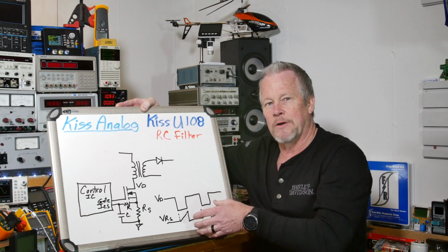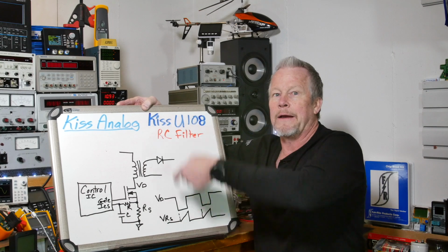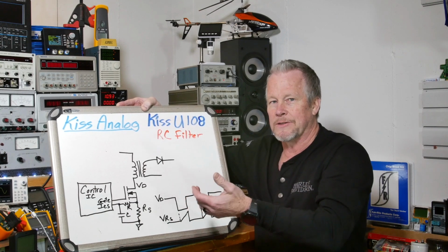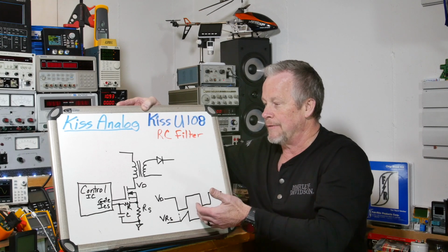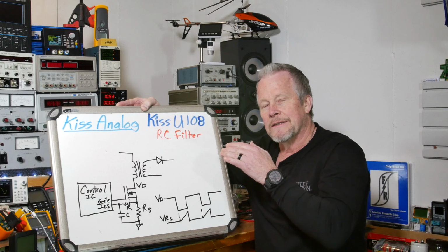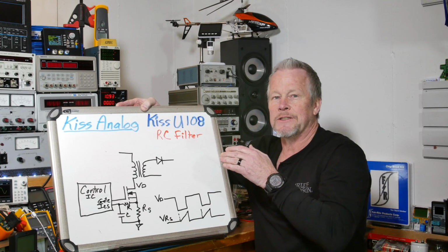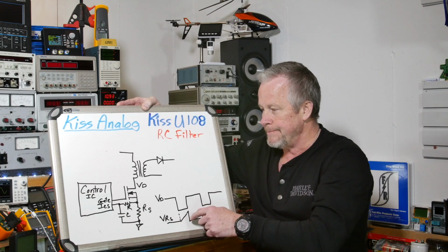It's just the inverse for an inductor. The voltage can flip. You get that kickback voltage, right? On solenoids and magnetics, you can get a kickback voltage that can be very high. But the current wants to not stop or change or start instantly. So it rises, it ramps up.